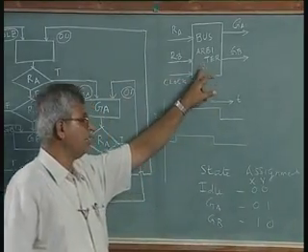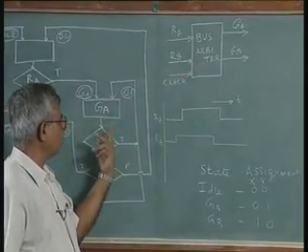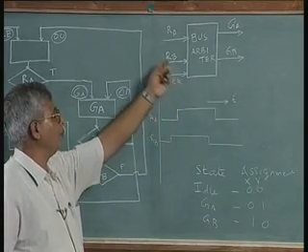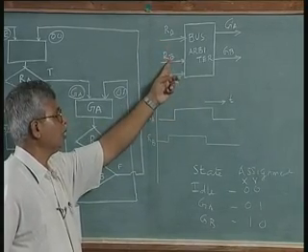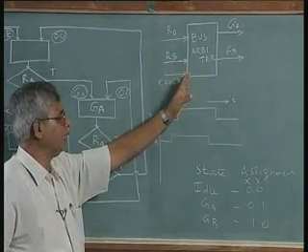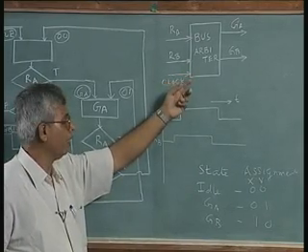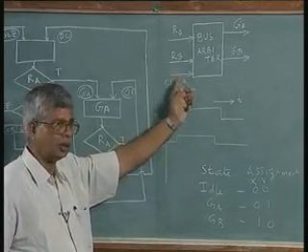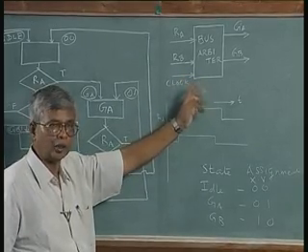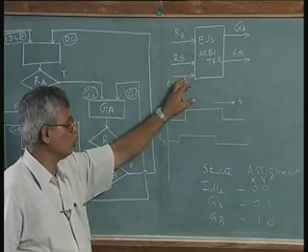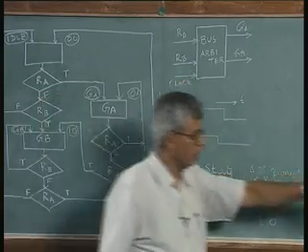The first time I drew this to draw the ASM, I did not show this because I only gave the specification of the problem. RA and RB are two input signals, GA and GB are two output signals expected, but then strictly speaking you should have included a clock. That is why today I remembered to put a clock also in this. Clock is an input that has to be shown always because the final implementation requires a clock, so a clock has to be shown here, as you see the clock is already there.